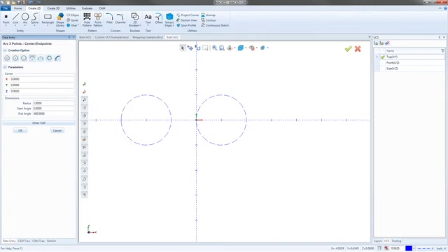Right here, we have a 3 points center endpoints option. So what we have is 3 points. So we pick all three of them, or you sketch first. So we're sketching kind of the radius. And then with this line here, you can drag how much of that radius you actually want. Depending on which way you go from, you can choose. So I could say, let's go back to right there. What's cool is that's not over yet. So I could say, you know what? I wanted to start at 0. So I can enter a 0 there. And we'll see that update. And I wanted it to go to 150. So I wasn't that close. But there we go.